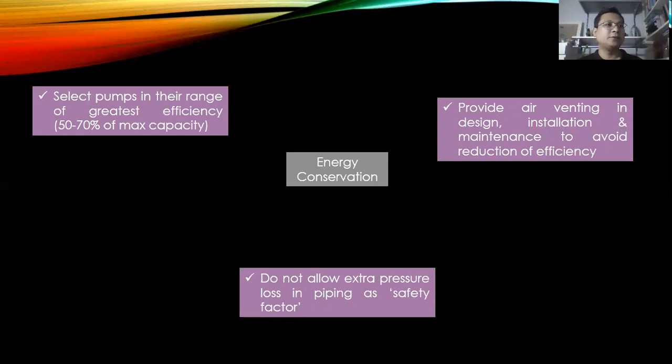We can reduce it by selecting piping and equipment carefully, because when we add more components in the piping, like valves, joints, elbows, anything, the head loss will increase.